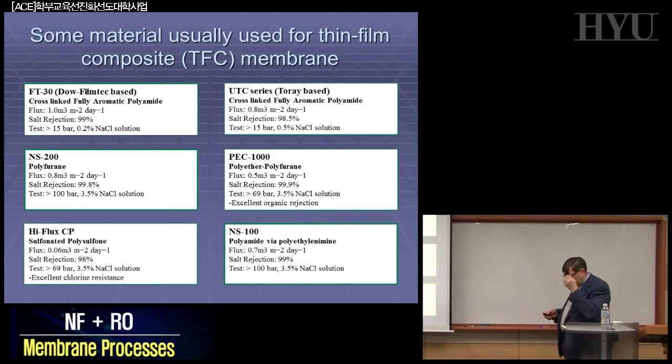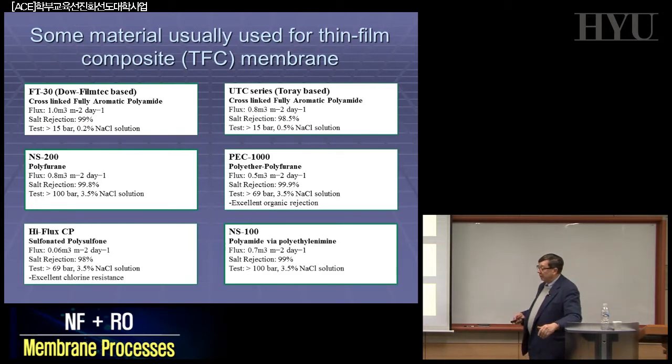It's a very sophisticated technology. Today, we understand most of the system, and by controlling the different parameters, concentration, temperature, kind of solvent, kind of non-solvent, quenching solution, etc., you can form an asymmetric structure. Very, very regular on large scale, and that's what is going on in many systems.